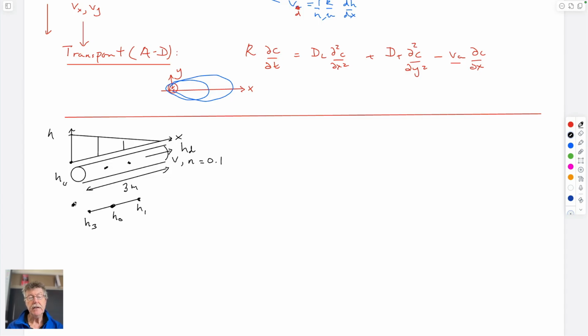So we'd like to be able to calculate this. We certainly know this head, and we certainly know this head here as well, because we're measuring it upstream and we're measuring it downstream, and we have those values. So we have some boundary conditions, upstream and downstream. What we don't know is what the heads are between those, and these would be the cross sections that we measure in the field, but we also want to calculate in digital form to figure out whether we're matching the permeabilities or not. So what we can do is make a model that represents that behavior.